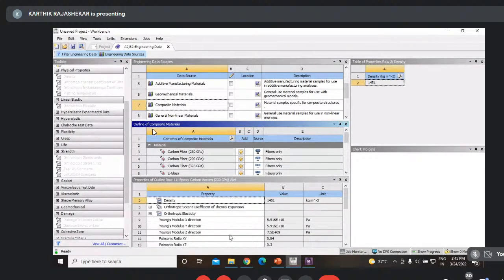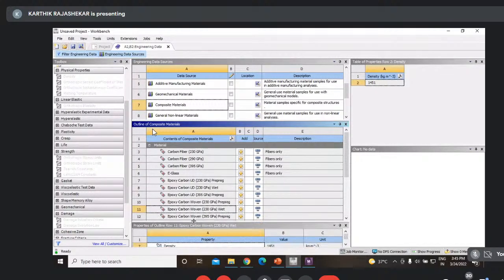Currently, I need to check where it is actually. So you can incorporate it, sir. It is possible. Okay, I'll check it, sir. Thank you. Or else you can do one thing. With some machines, like a Zwick testing machine, it directly shows you the Young's modulus. Or else you can incorporate the stress strain data in Excel software, generate a stress strain curve. From that, you can generate the area under the stress strain curve, which indirectly gives you the Young's modulus. That is the option you can do.